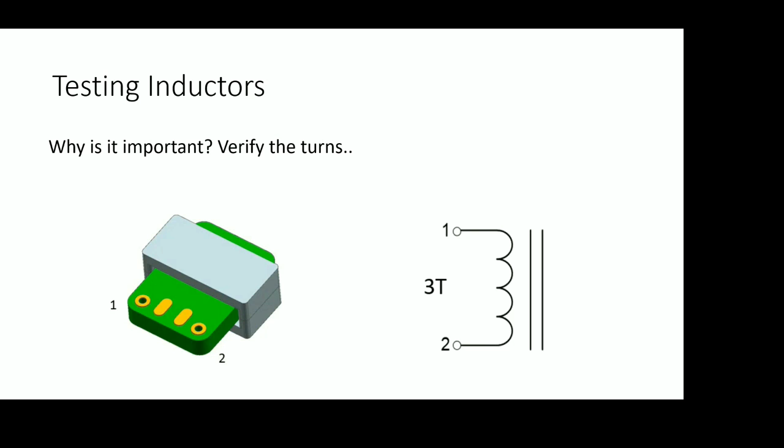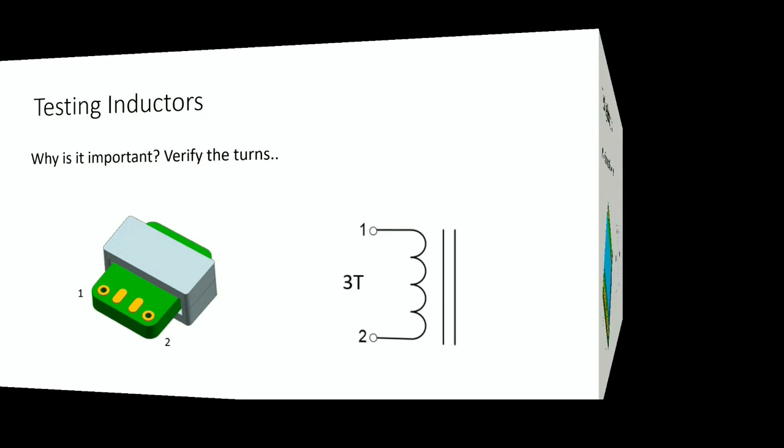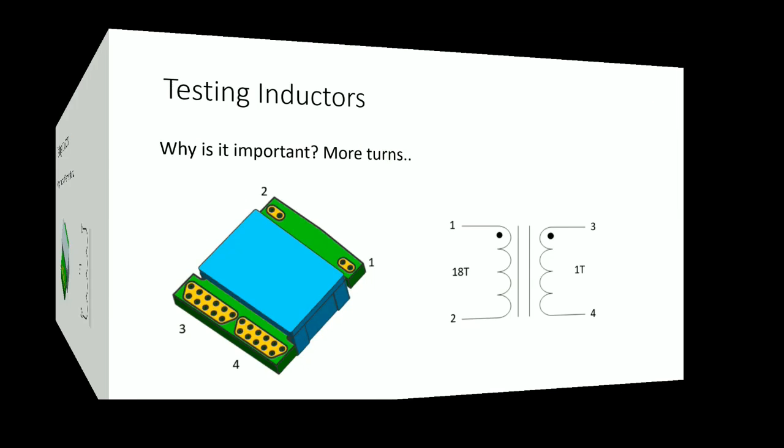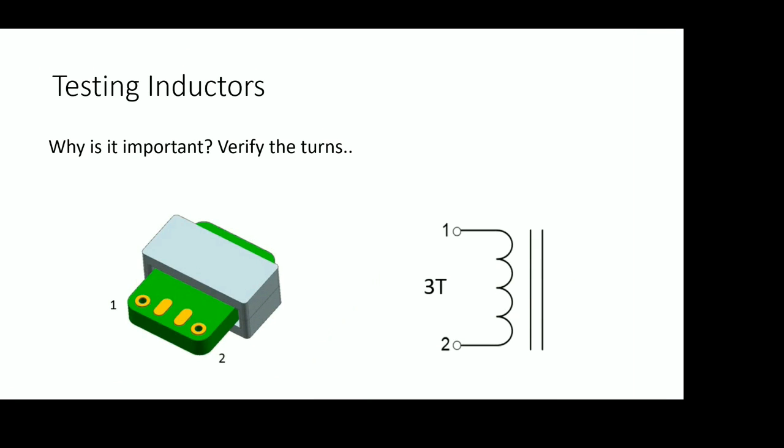That's correct, Todd. Very nice. So when we're talking about inductors, I got ahead of myself. We talked about turns earlier. If you have turns around a primary, turns around a form, whether it's air or ferrite or toroid, that combination there, the core permeability against the turns, gives you what you're going to get for your inductance in henries. When you have just a standard coil, that's what it's going to be.